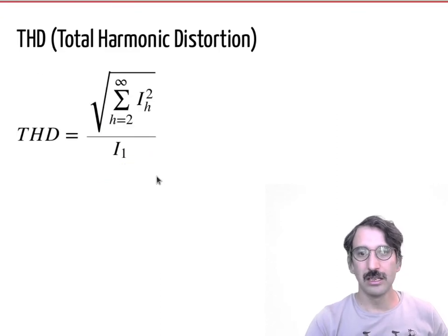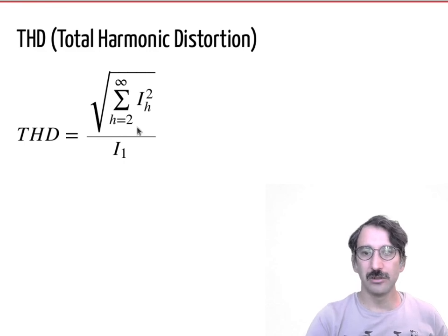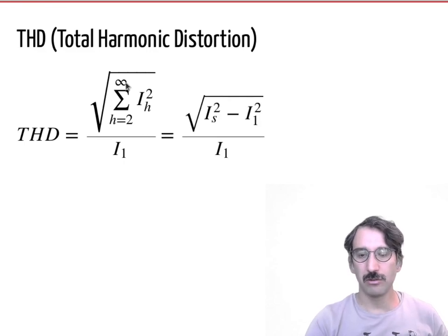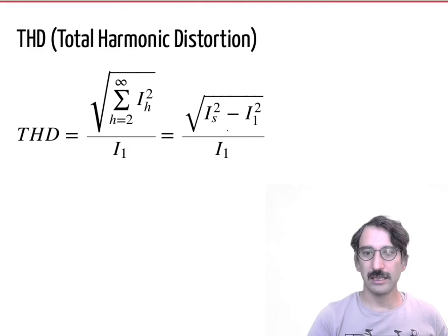Okay, so again, THD can be written as the ratio of the total harmonics, or you can get the total RMS of that signal, which is the equivalent RMS of that waveform, and subtract the fundamental, and then divide by the I1 RMS.